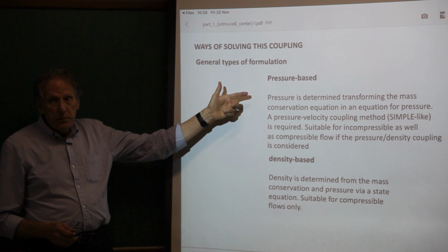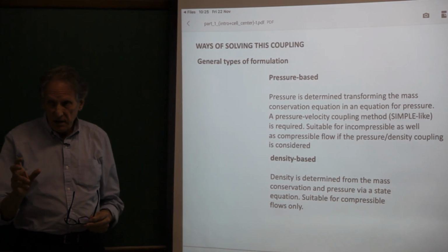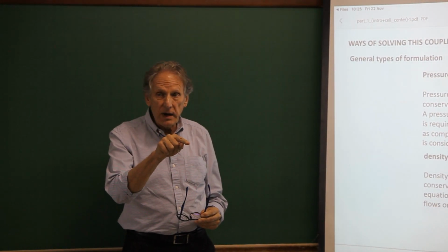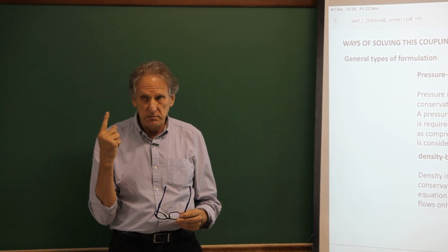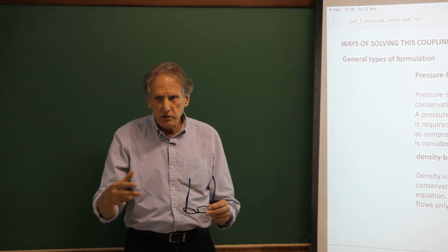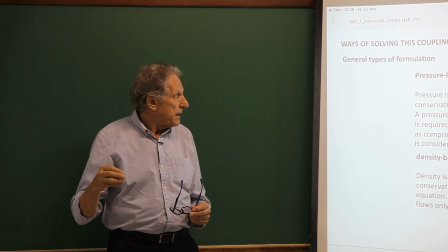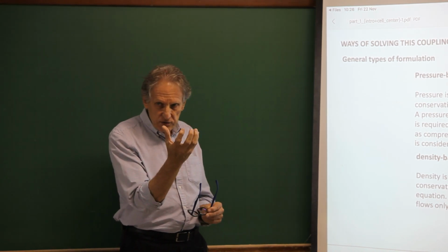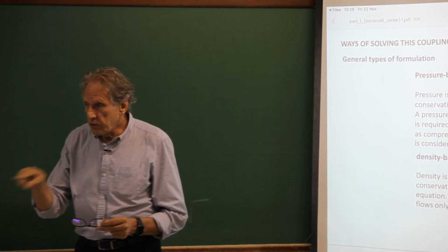What are the pressure-based methods? The pressure-based methods are the ones that transform the mass conservation equation into one equation for pressure. There are several algorithms you can do, but a pressure-based algorithm is the one which picks up the mass conservation equation and transforms it into an equation for pressure.